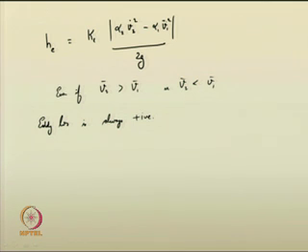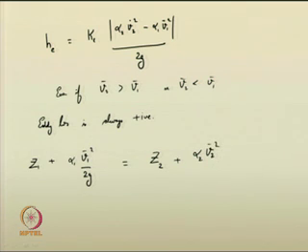So, what do these relations suggest? You can see that Z1 plus alpha 1 V1 squared by 2g is equal to Z2 plus alpha 2 V2 squared by 2g plus friction loss plus eddy loss. Like this I can easily write it.